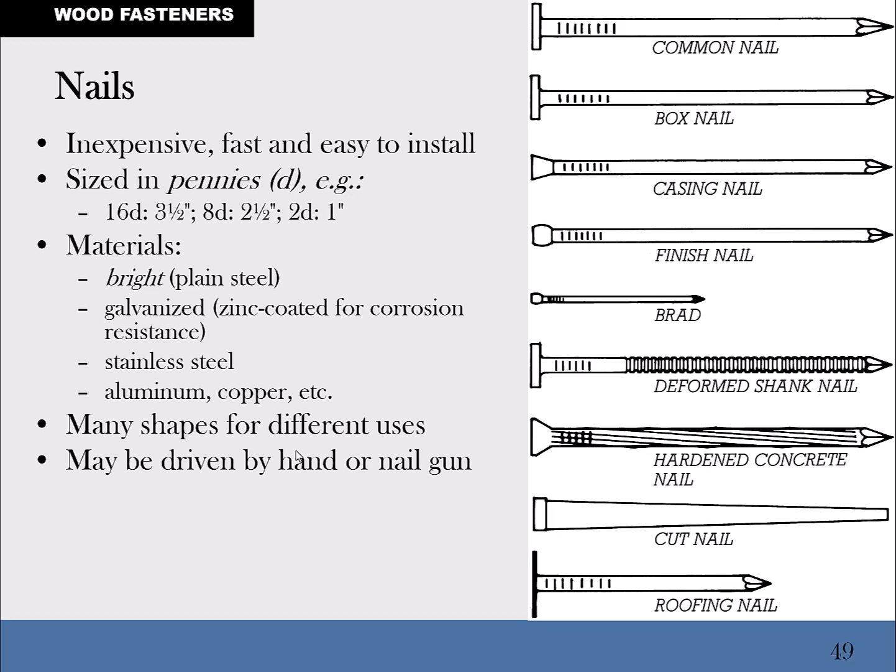And so nails are relatively inexpensive fasteners compared to other fasteners. They rate them by length and the diameter of the shaft with a traditional nail. So a traditional nail that you actually hammer in with your hand, a 16 penny nail, 16D nail, it's going to be a little longer and a little bit bigger diameter than a 12 penny nail. So a 12 penny nail is 3 1/4 inches long. A 16 penny nail is 3 1/2 inches long. But the shaft is a little less.